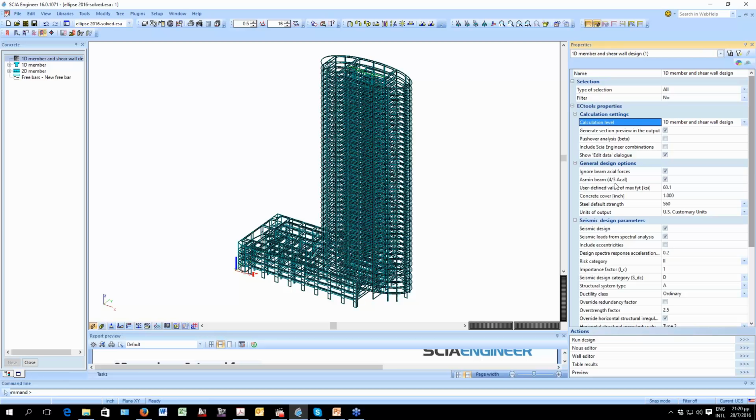The minimum beam flexural reinforcement is 4/3 of the calculated reinforcement or not. The other choice is to go with a different approach of ACI. We have it checked here, although it is suggested to be used only for large cross-section beams, like in bridge girders. But because all other software use that, we tend to use it for comparison reasons.